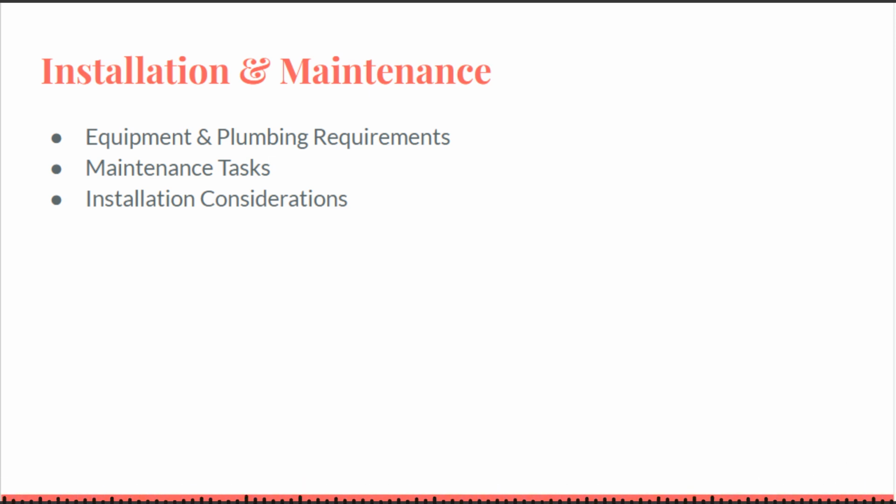Installation considerations. Safety devices like a flow switch, interlock, or vacuum pressure switch are often built in or recommended to ensure ozone doesn't flood the line when the pump is off. As noted, water flow must be sufficient.